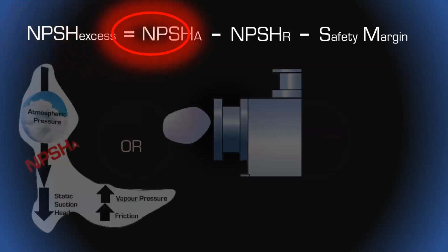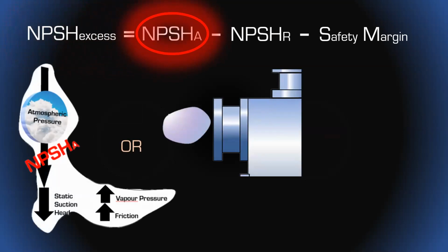So again, let's take a look at that NPSH available. If we have a suction filter, I'll ask you, Chris, I can't ask anyone else. If we have a suction filter, will that affect, do you think, or possibly affect the NPSH available on this pump? So anything that's attached to the suction pipe that's going to increase any kind of restriction, which could increase our friction losses, is going to end up in that calculation as a friction component. So good. So any valving, anything extra is definitely going to affect that NPSH available.